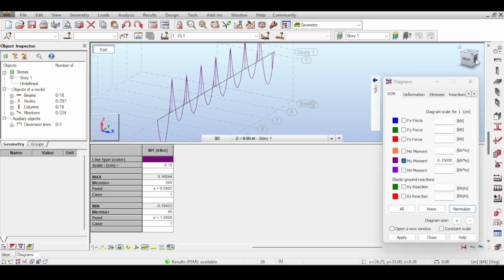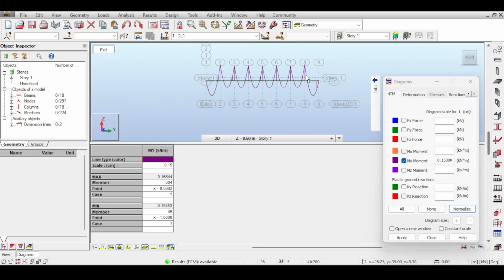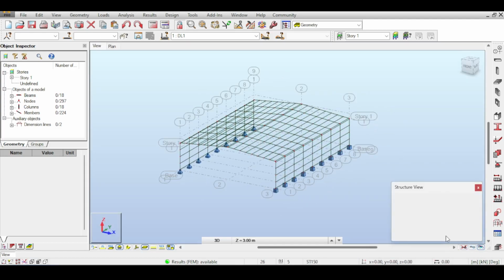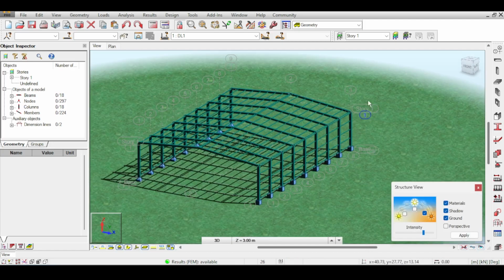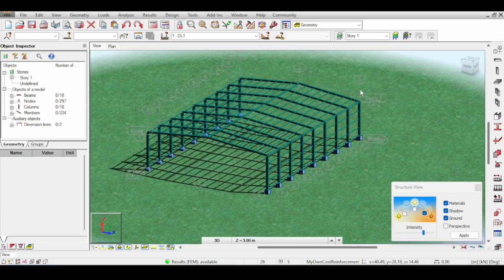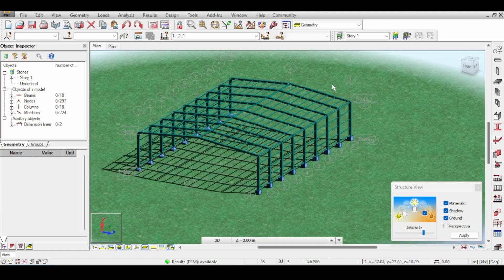So yeah, you can see the purlin is continuous. There is frame action. That's not what you want. So this is utter garbage. I mean, look, the structure looks really cool. I can make a very cool, clickbaity thumbnail. As a matter of fact, I will use this as a thumbnail. But it's utter garbage because we still need to modify that, right?